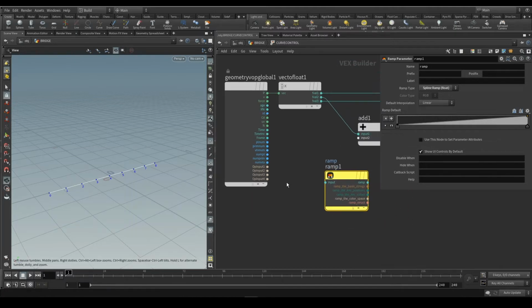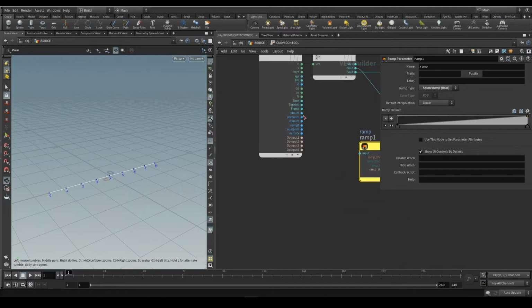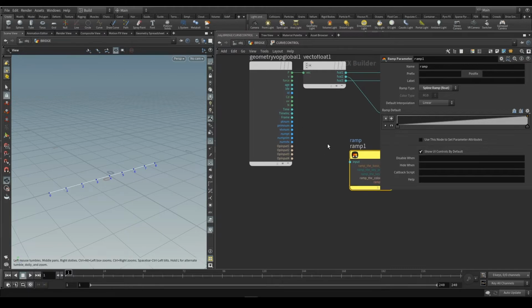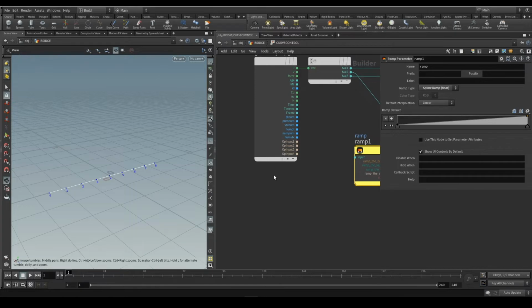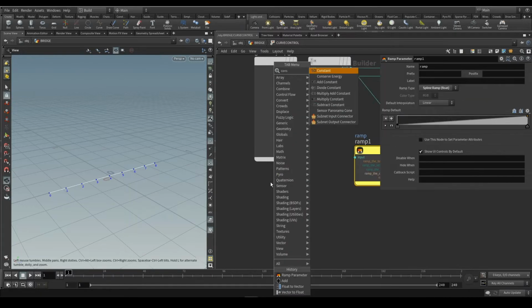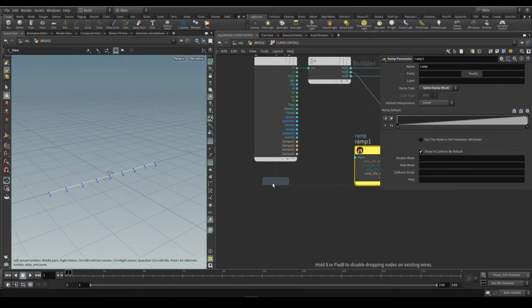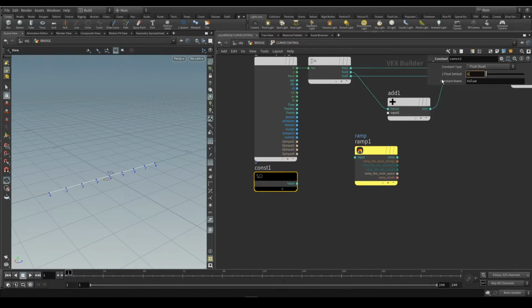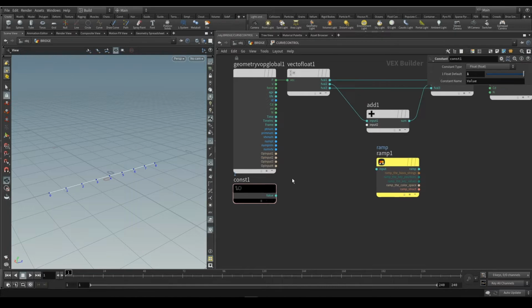So as we have int, if I divide int by another int, I will have an int output, so it will stay 0. So I have to convert by a simple trick. I will multiply by 1, a float by 1, so the node will become like this one, that green color. That means that it's a float.